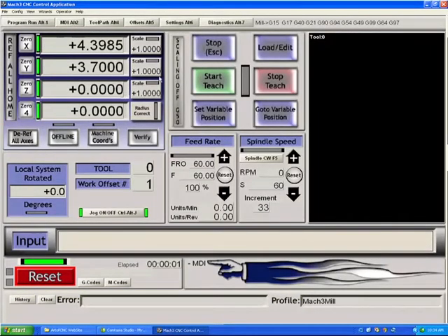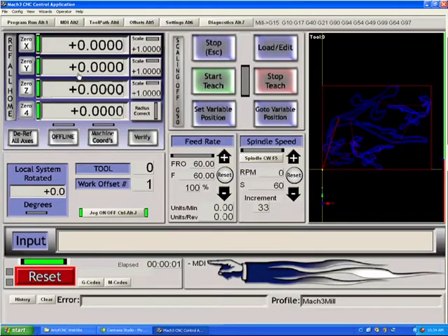If we take a look at the MDI screen, again we have our DROs repeated. It's handy to have DROs on most of the screens so you know exactly where your table is at. We have 0 buttons for zeroing the axes and another reference button here, the scaling. Radius correction is used for 4-axis work, where you can tell the system the actual circumference size of the object, and it will correct the feed rate to create a toolpath that feeds at the correct rate on the circumference of a rotating object. Again, something that you can ignore unless you understand what they're for.